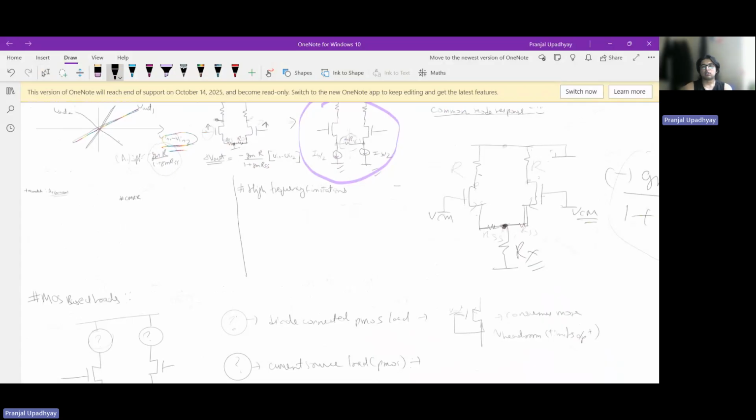It can be threshold voltage mismatch. It can be the beta factor, which is mu n times Cox W by L, that gets mismatched due to various things. It's a rather complex process, so we won't go into why it all happens. The basic idea is that realistically nothing is ideal, and thus even assuming the system parameters are perfectly symmetric is a big assumption.